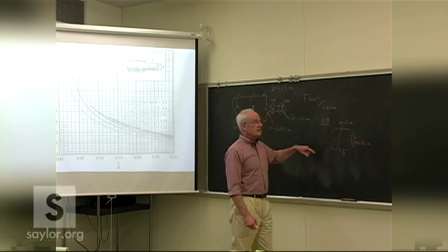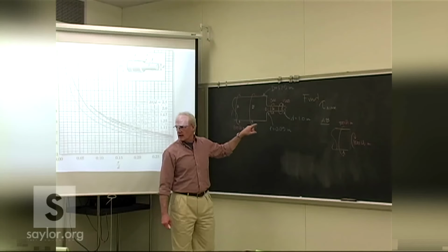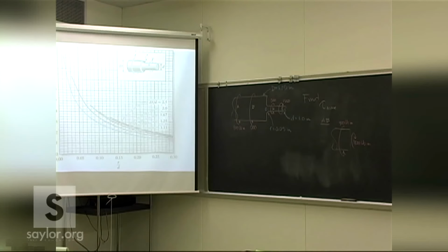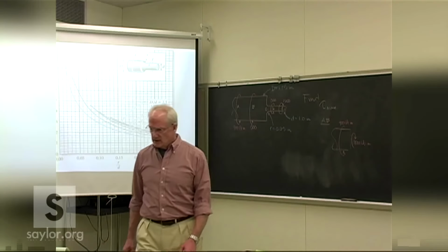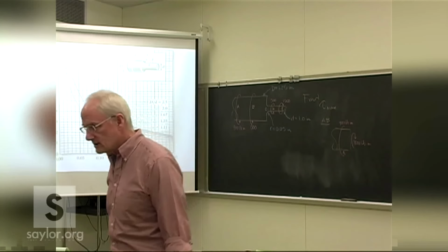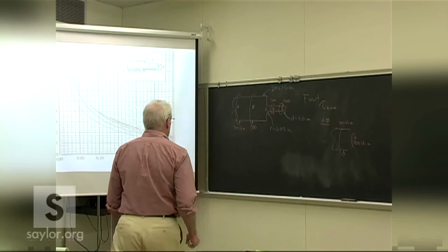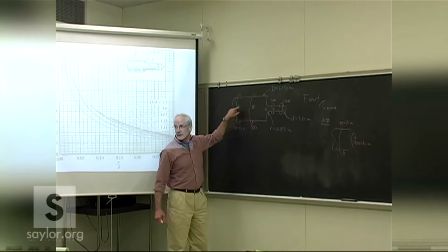This doesn't seem like too much of a worry because there's other places with greater load and smaller diameter. So the suspicion would be A to B is not going to be the limiting region. Some other region will be. So that's a pretty low load on a pretty big diameter, not of great concern. Do we actually want to take the average, or just use the greatest one? No, you have to look at what's happening in each section.